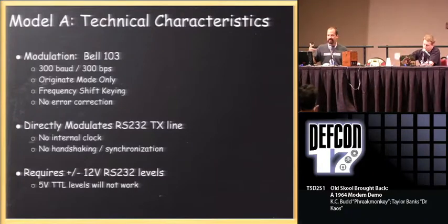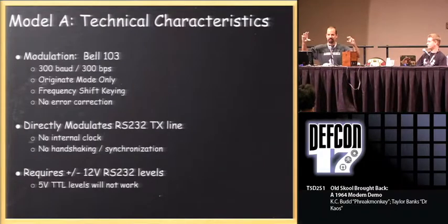The other thing that the IEEE standard says is when you transmit RS-232, you do it at plus 12 volts when you're idle, and then negative 12 volts for bits across ground. So it's a 24-volt swing between idle and bits. And they said the receive side needs to be able to discriminate and decode plus 3 volts to negative 3 volts or greater. So you've got this great discrepancy in what is allowable in there.